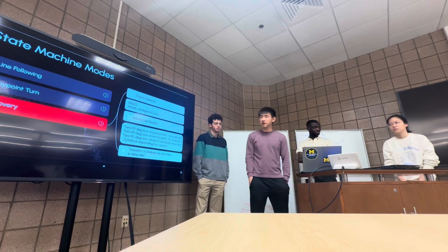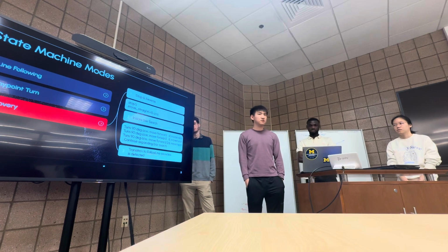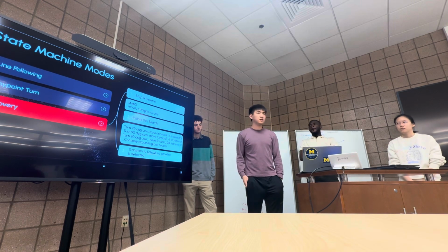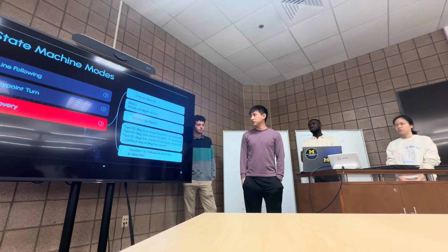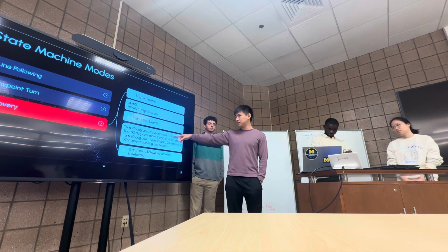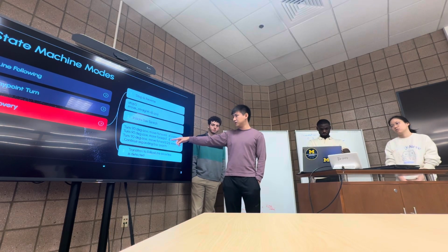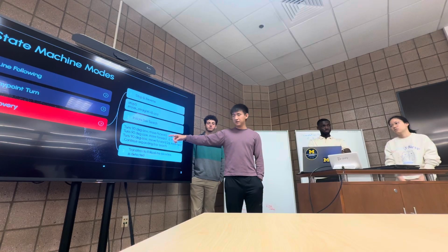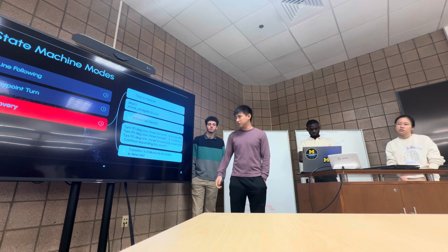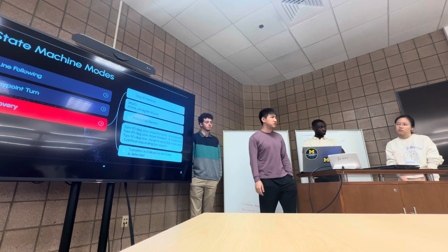And this is the recovery mode. If we get lost, we'll stop and move backwards by a set amount, which is just a variable we have to figure out through testing. Then we'll initiate a box search where we turn and move forward a set distance D. If we haven't found it yet, we turn again and move forward D, then turn again and move forward 2D, and this continues expanding. This keeps going until follow line is detected.